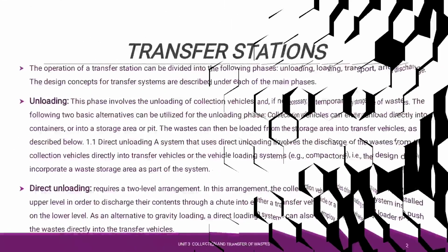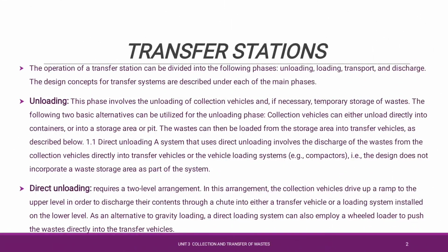First, let's see what a transfer station is. A transfer station is a place or location for unloading the waste from each individual collection vehicle. From here, the waste collected from individual houses is reloaded into a larger vehicle so that the waste can be carried to the disposal site as well as to the processing site.